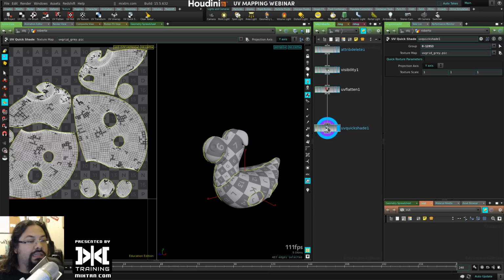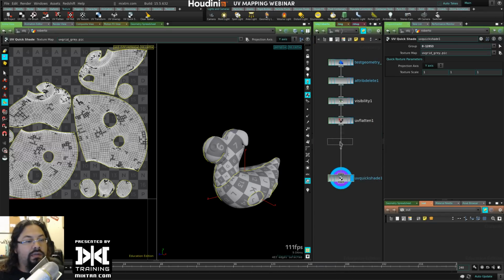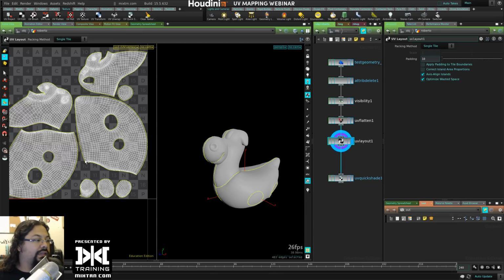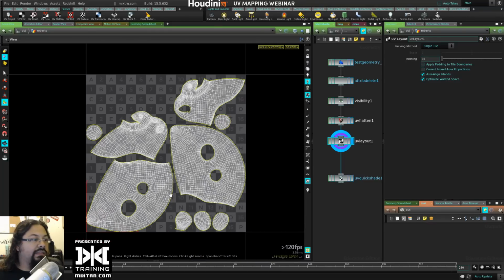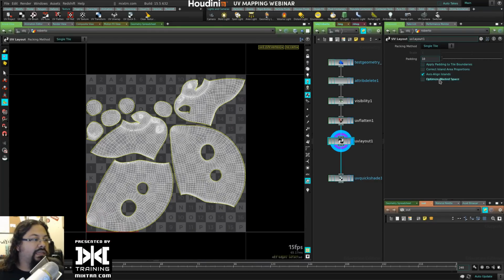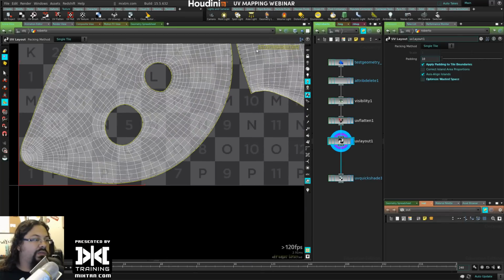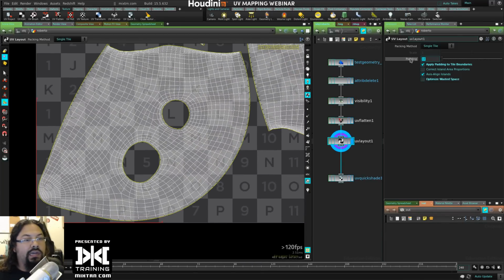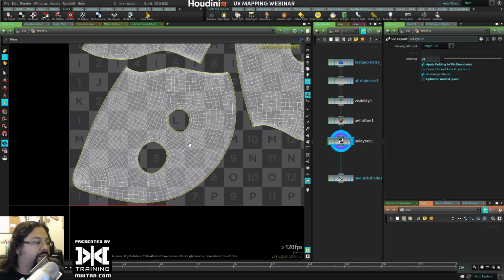So what you can do is, let's say we want to lay out this. There's the very useful UV layout node now. See that arranges your UV islands here. Tries to not waste any space. Just to make the most of that. And then you can apply some padding, because it's always important to have some padding between the islands and the borders. I always put this like around 20 if I'm going for more than 2K or something like that. 20, it's a good number for me.